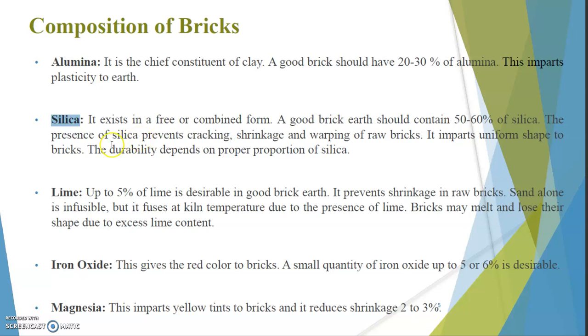The presence of silica prevents cracking, shrinkage, and warping of raw bricks. It imparts uniform shape to the bricks. The durability depends on the proper proportion of silica. In the same way, what is the role of silica here? It actually plays more roles than alumina. The presence of silica prevents cracking, shrinkage, and warping. So they are telling three different phenomena.